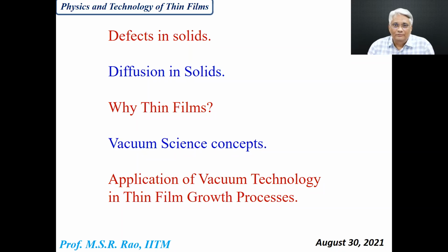And even in the process of sputtering, or any other PVD or CVD method, the substrate, the base material on which the thin film grows, when the atoms come on the base material and settle down to their lattice positions, high temperature facilitates the nucleation and growth process. Well, the temperature required to grow a crystalline thin film is not as high as